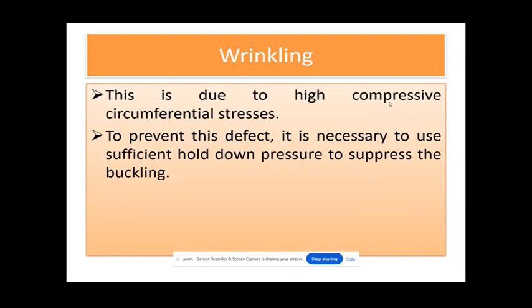Wrinkling. Wrinkling is due to compressive circumferential hoop stress only. To prevent this defect, you have to apply sufficient hold down pressure to suppress the buckling or wrinkling.